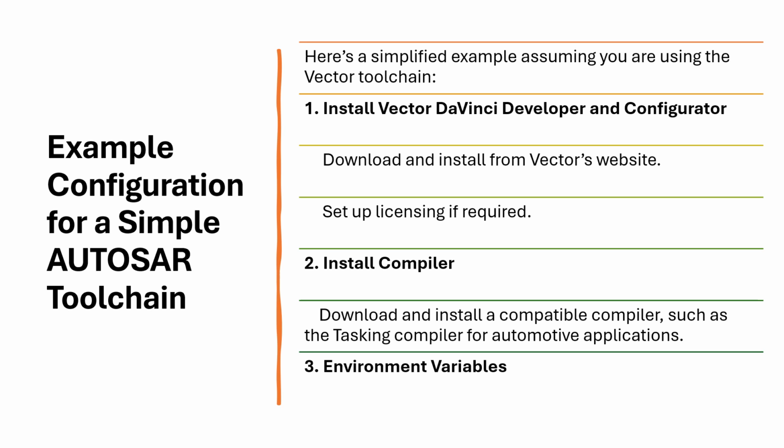Then generate the RTE. DaVinci Developer generates the RTE, the runtime environment, based on the defined software components and the base software configuration. Then build the project using the build function in DaVinci Developer or an external build script. And finally is flash and debug. Use Vector's flashing tool to program the microcontroller, and then debug using a compatible debugger.